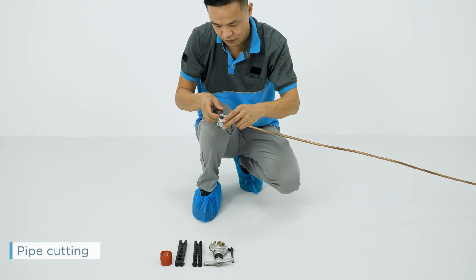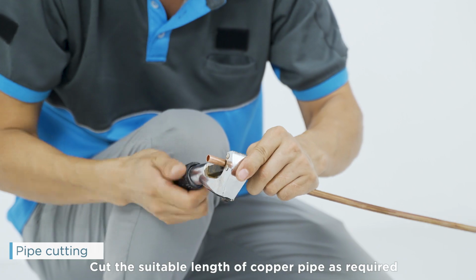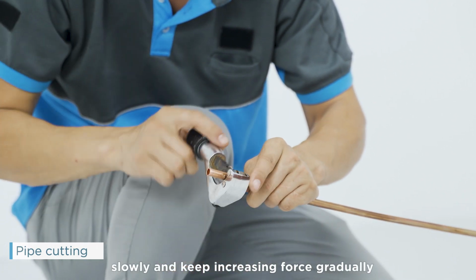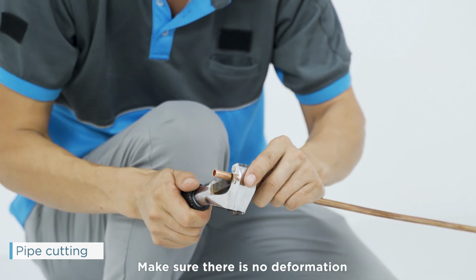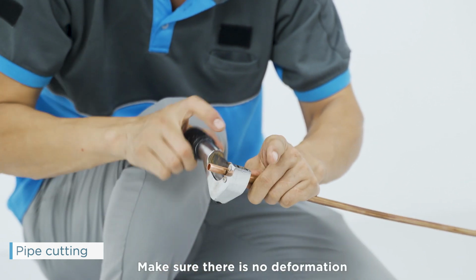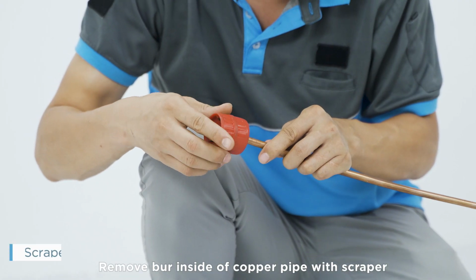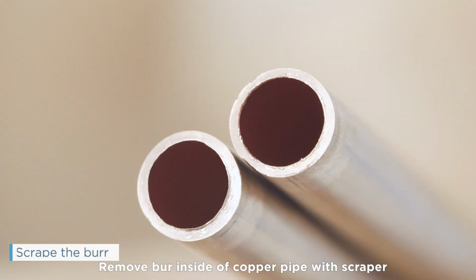Pipe cutting. Cut the suitable length of copper pipe as required. Turn pipe cutter slowly and keep increasing force gradually. Make sure there is no deformation. Cut surface should be level. Remove burr inside of copper pipe with scraper.